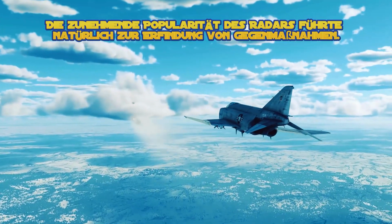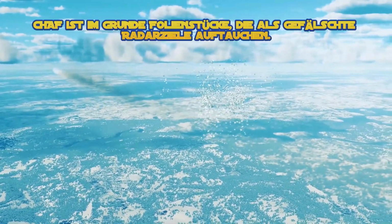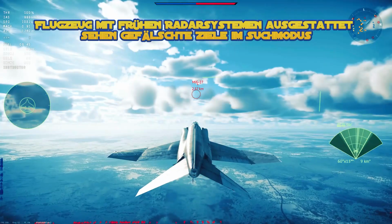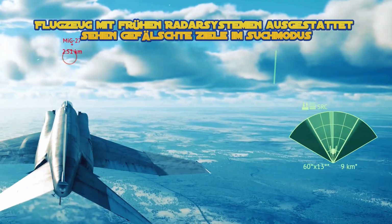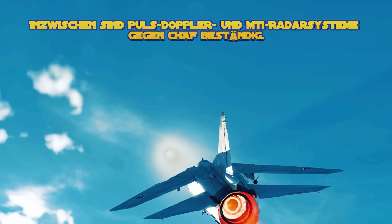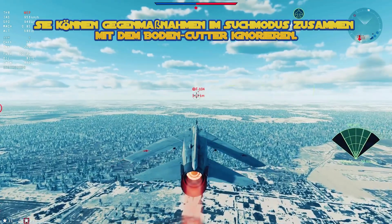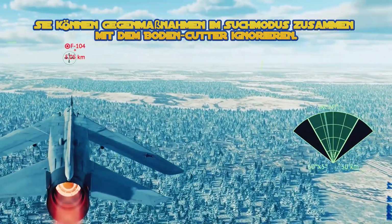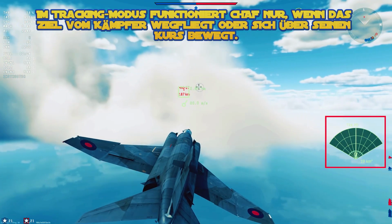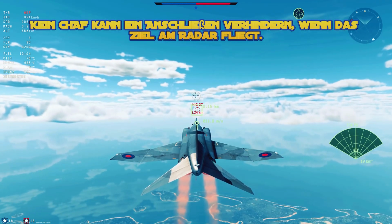The increasing popularity of radar naturally led to the invention of countermeasures. We call it chaff. Chaff is basically pieces of foil that show up as fake radar targets. Aircraft equipped with early radar systems see fake targets in search mode and have troubles in tracking mode as well. Meanwhile, pulse Doppler and MTI radar systems are resistant to chaff. They can ignore countermeasures in search mode, along with the ground clutter. In tracking mode, chaff only works if the target is flying away from the fighter or moves across its course. No chaff can prevent lock-on if the target is flying at the radar.